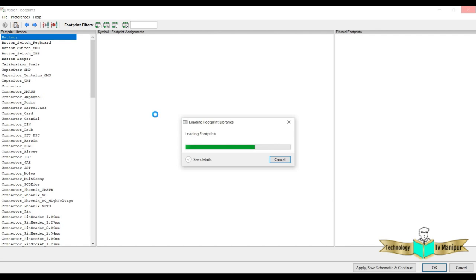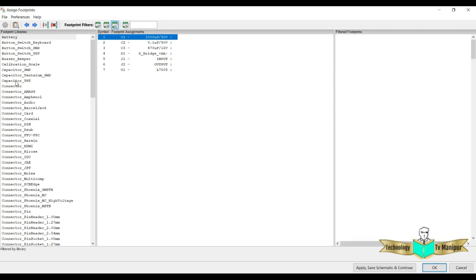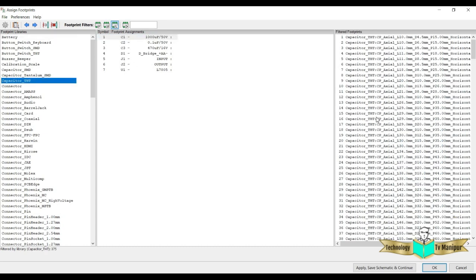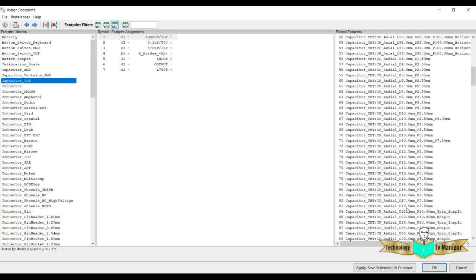But in this video, I would like to complete the task by creating a Gerber file. So let me continue with the existing footprints available in the KiCad software. Okay, so we opened that schematic here, that is C1, C2, C3 all here. This electrolytic capacitor is usually through hole. So we can go to capacitor through hole here, and these kinds of capacitors are all radial capacitors. You can go directly with the radial capacitor, and 1000 microfarad is quite a big capacitor, so I can go with a little bigger size of say 18 mm diameter.